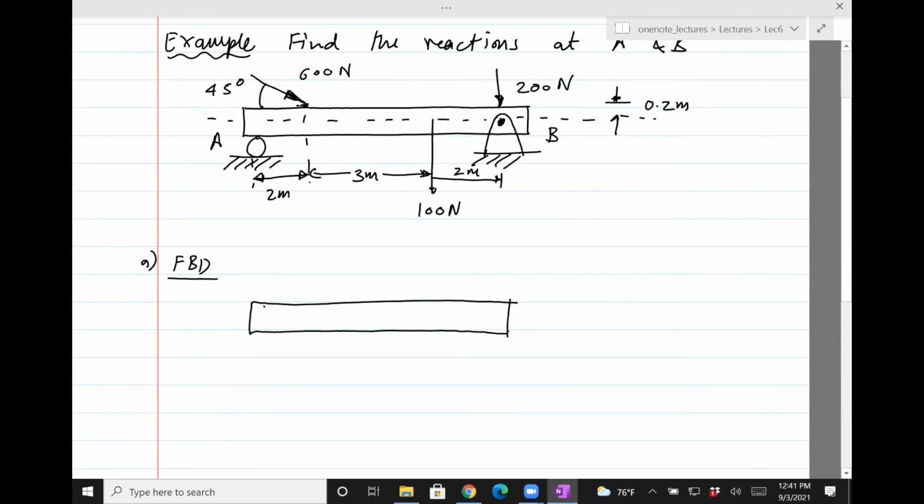Now we got to go back and review what reaction forces occur due to roller and pin joint. For the roller, there's going to be a force in the vertical direction. I'm going to use a slightly different notation here: V is vertical, to show X and Y. So the force in the vertical direction at A is VA, and that's the only force.